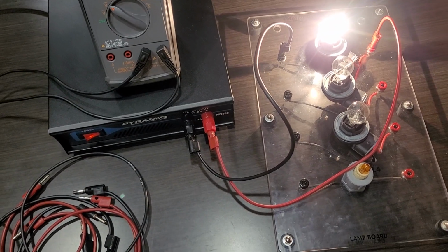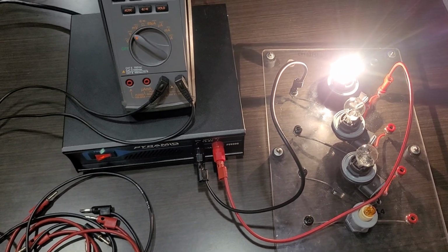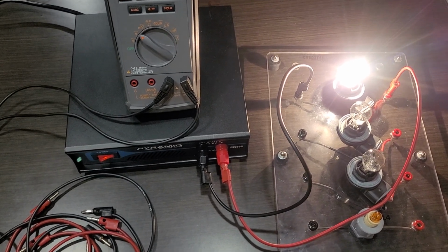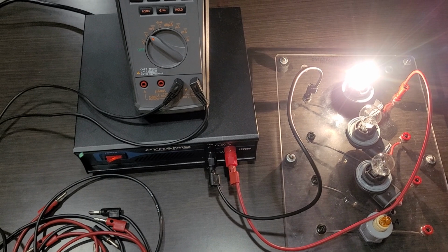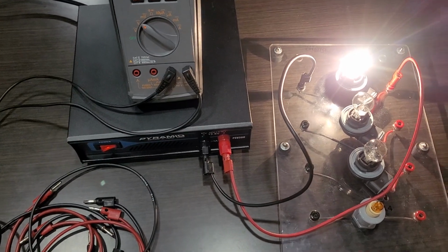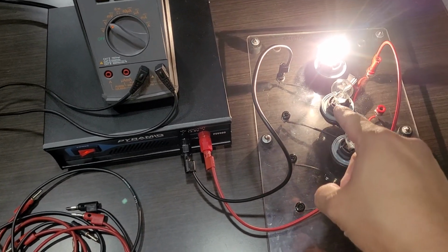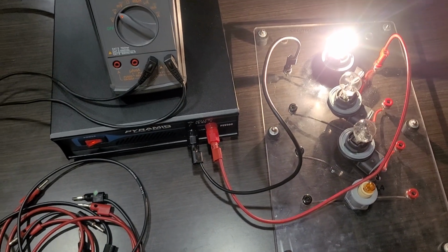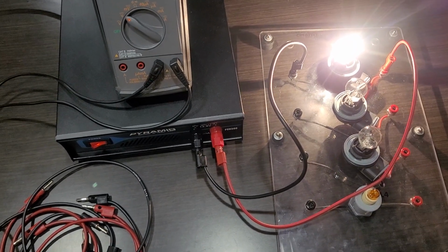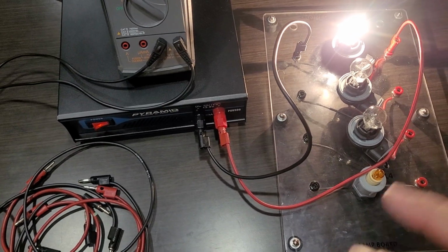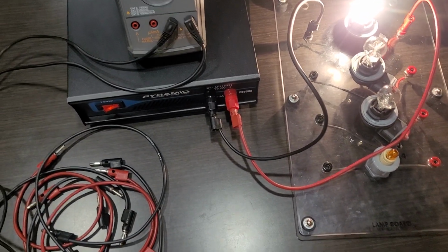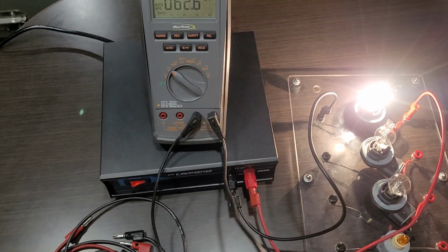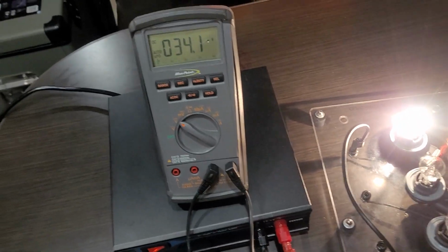So for example, it could be anything from a window motor to a blower motor or a horn, okay? Some of those you cannot see visually like a light bulb. Now obviously the horn, it's not gonna light up, but you will hear it. And a motor, if it's very quiet, you won't even hear it, and you can't see it functioning. So you have to do the test. So I'm going to take one of my test leads here, the one on the volts.